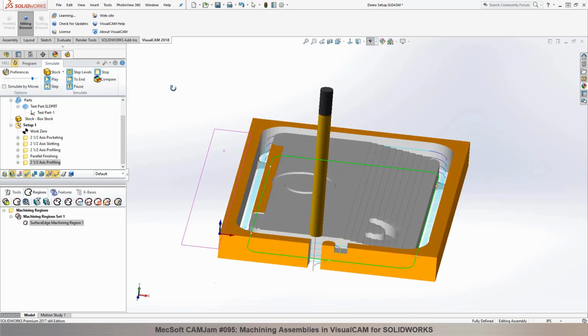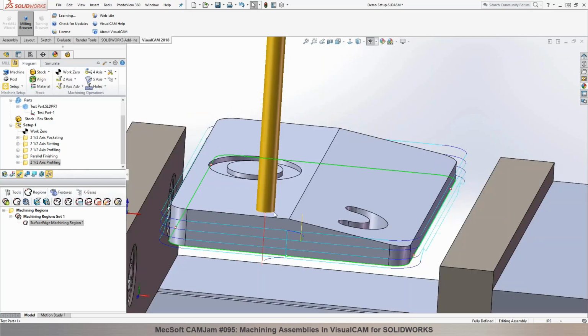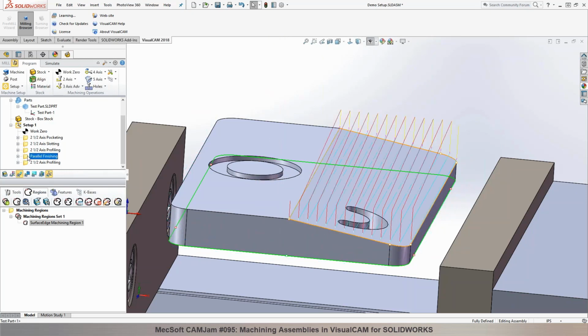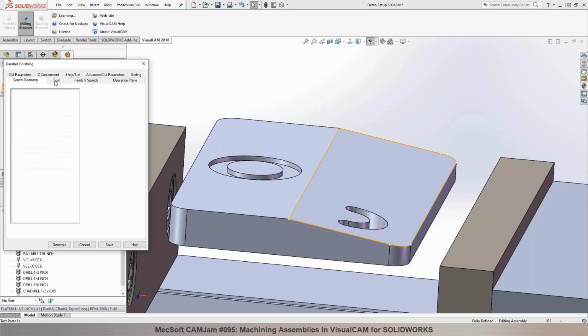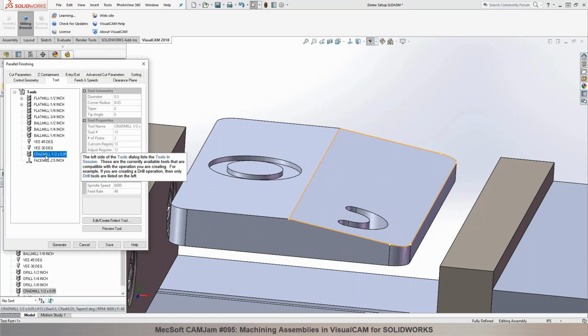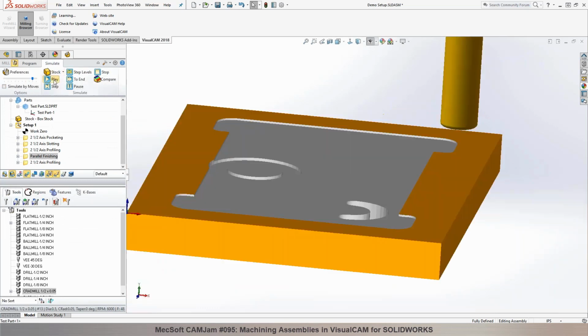That doesn't look like the draft there has the... Yeah, because I used a flat mill here, I should have technically used a ball mill to finish it because you have a draft on it, right? To get a better finish, you probably want to use a ball mill tool. Or even a corner radius tool might work better. So you can go into the tool, you can switch this from a flat mill to a corner radius tool, and it can go with a really fine step over, like 10%. So that'll give you a very nice finish on it.